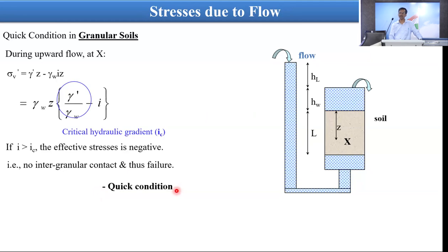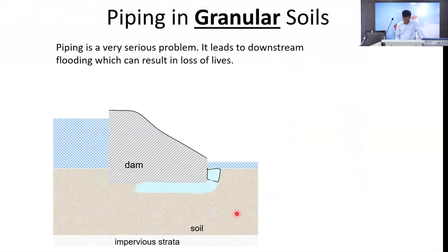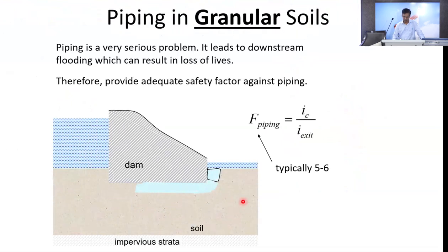So this is another aspect when I am talking about permeability, because in consolidation it is related to the stress, there I am talking about it because the void ratio is changing. In permeability we generally didn't discuss what is happening to the effective stress at different points if there is a steady state flow. So these cause a problem, and that is what Dr. Panda will discuss. And finally this makes a piping in a dam, and this piping is critical,